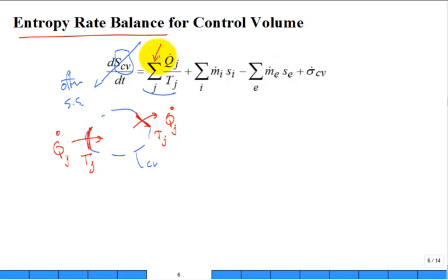And we have the rate of entropy production inside the control volume. Those terms are familiar. But what's new when you have an open system, you could have mass flow taking with it both energy, first law, and entropy, second law. So it brings in its entropy as well as taking out its entropy. So these are the new things with the control volume. Does that equation make sense? Does it look pretty easy, straightforward?